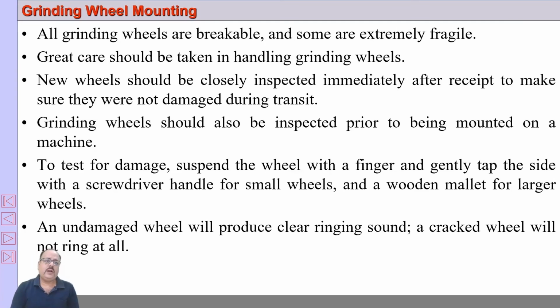Another very important factor regarding the grinding wheel, two aspects, is wheel balancing and wheel mounting. These two are very, very important. When you are going for grinding, you should mount it very carefully, and you should test the wheel for any kind of internal fracture. Normally we strike the grinding wheel with a wooden mallet, and by the sound, if it gives a clear ringing sound, that means the grinding wheel is perfect and sound. If it gives a dull sound, that means there is some internal crack, and that cracked grinding wheel should not be mounted.